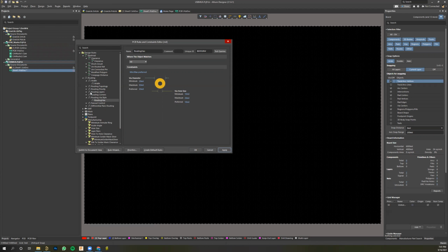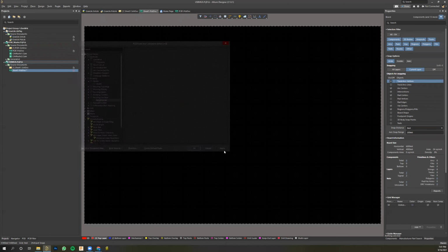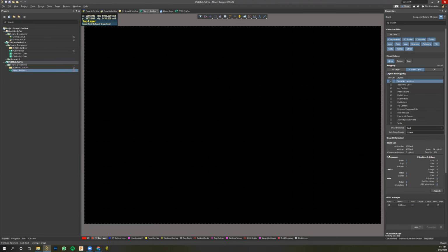I actually have a question. It's not on the rules themselves, but mine is set to mm. How do I change it to mil? I've tried inputting it manually, like there, but it doesn't let me. Good question. Let's find something that has dimension on it. You see right here where it says board size, and it says it in mil.